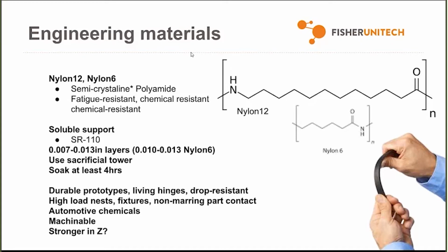Nylon is a pretty viscous material when it's heated, so the machine needs to apply a lot of pressure to the filament in order to print reliably with it. That makes it hard to start and stop extruding. So the model tip is prone to drooling, where a little bit will kind of ooze out, and that drool can knock thin parts over, tall parts over, and it can affect the surface finish of your parts, and it can cause some other problems too.